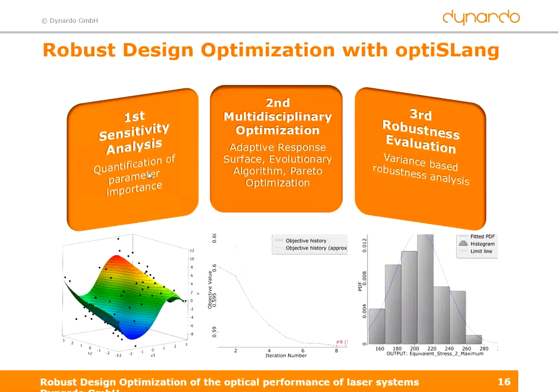You will always start with a sensitivity analysis to understand your design. Afterwards, you might do an optimization, because the sensitivity analysis will help you to find out first which parameters are important and will have a real impact on your responses. And you will also find out how your objectives are in conflict or not.